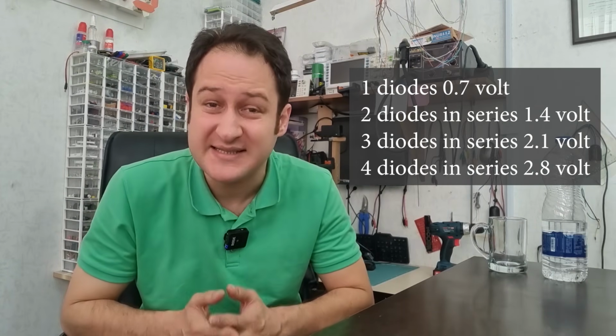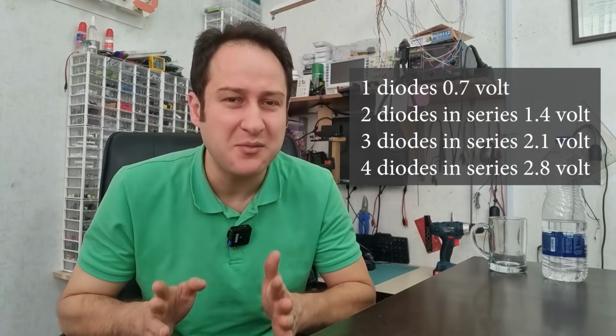This approach for reducing voltage is not the best way, but it has its own advantages. It is super simple and cheap, and you can use a bunch of diodes in series to reduce more and more voltage. But you have to be careful. If you use many diodes in series to reduce more voltage, the impact of current on voltage drop will be impressive.